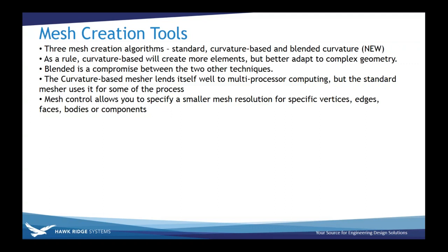One we call standard, that's the one we've had forever. Curvature-based, which we introduced in about 2008, so it's been around for a while, which looks at the local curvature of the model and scales the mesh to match in that area, and a blended curvature model, which is relatively new.